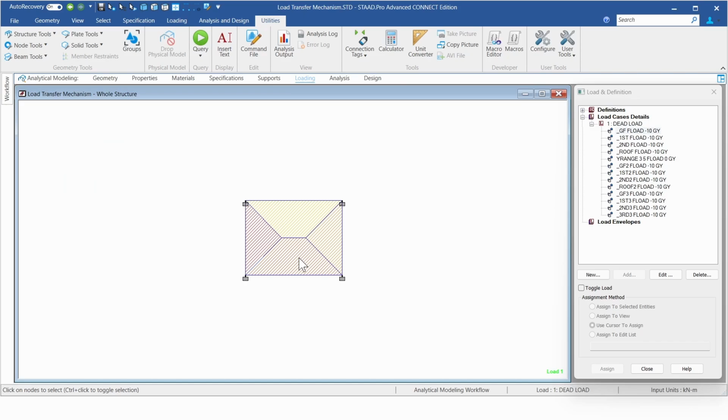Now, this is going to be a two-way slab. I've designed it as a two-way slab, thereby giving me the opportunity to transfer the load onto all the beams. So each beam right here, 1, 2, 3, and 4 beams are taking loads, which is described by whatever you're seeing right here. So this beam is taking this triangular load. This beam right here is taking the other part of the triangular load. This beam is taking this trapezoidal load, and this beam is taking this trapezoidal load. If I were to go to the front view, you'll be able to see what I'm talking about.